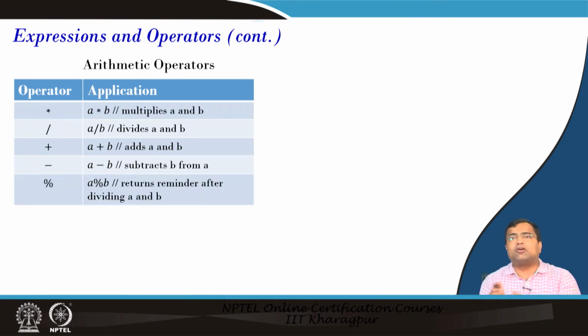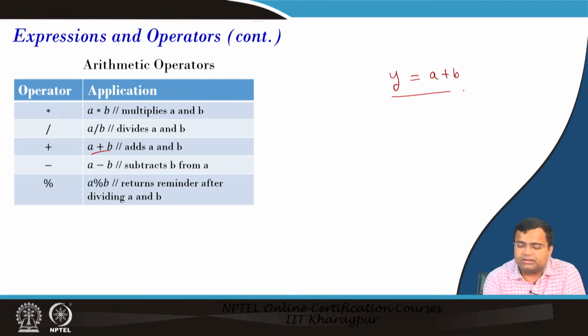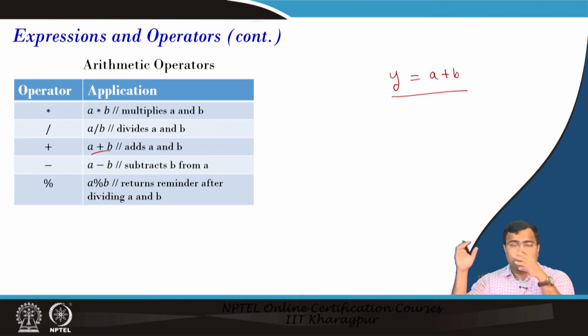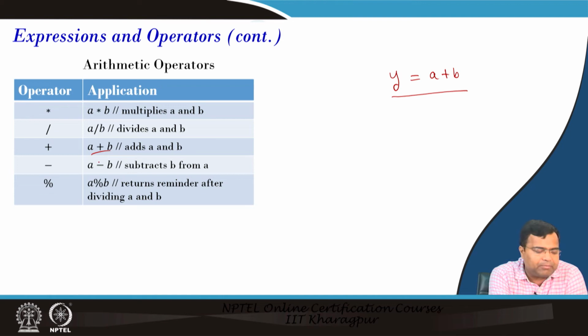Okay, then arithmetic operation. This is also very interesting and we will be using it, because we talk about adder circuits. We want to add, y equal to a plus b. This is simple addition of two numbers, but we have to consider that this is not just an adder, because we have to take care of the carry out, carry in, and sum. So how does it look? We should remember this plus symbol indicates an adder.